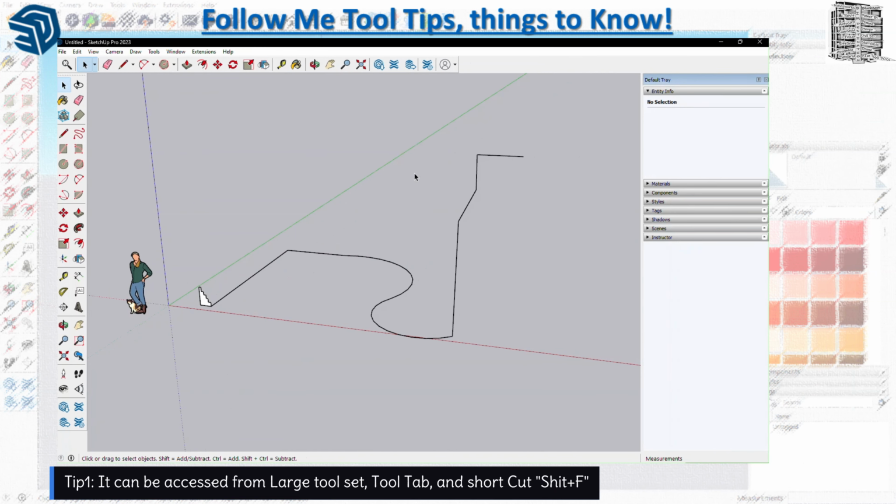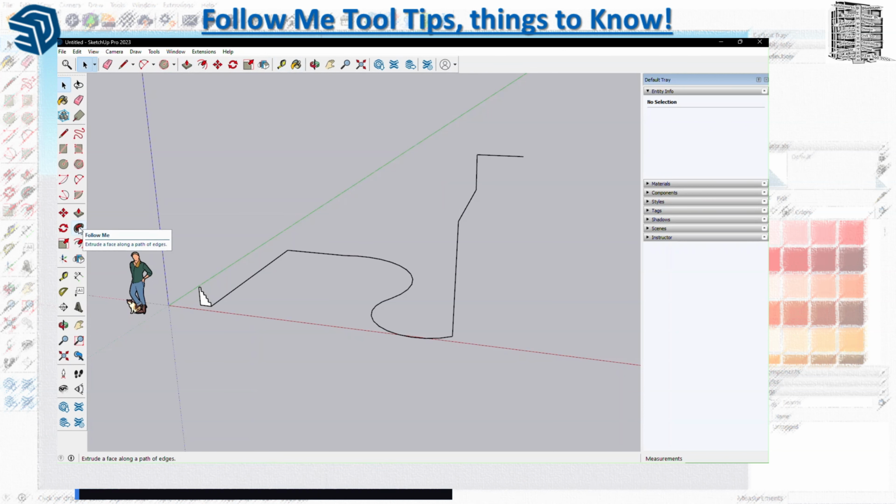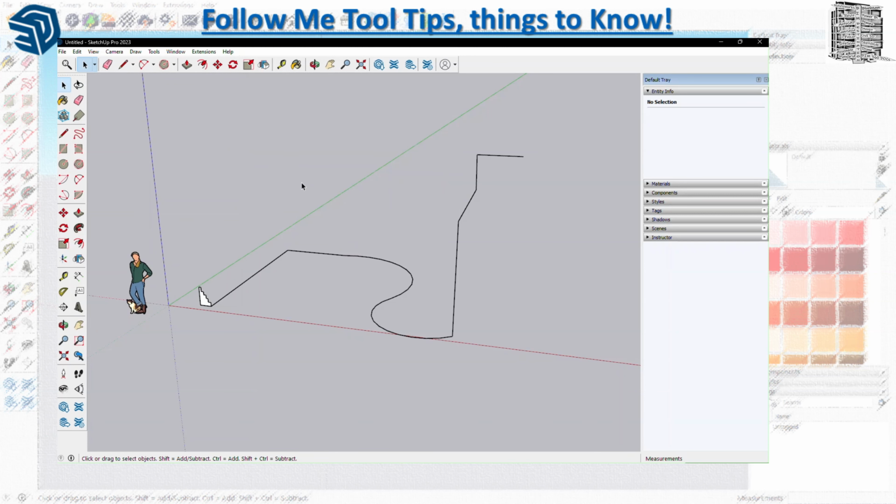For the Follow Me tool, first we want to take a look at the location. You cannot find it on the default toolbar. It's only available on the large tool set, and we all know how we can get the large tool set. Also, it's available on the Tools tab, Follow Me, and the shortcut key is Shift F. So just make sure you do that.